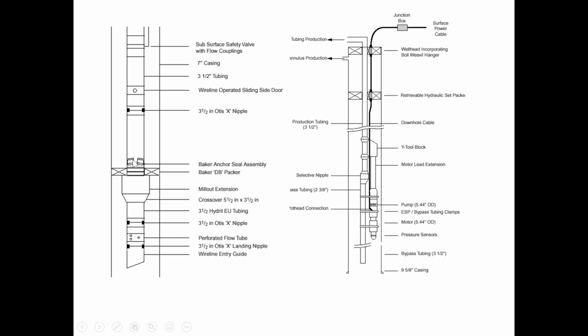And in this anchor, as I said, sometimes you just need to take the tubing out, not the packer. So we have a seal assembly, and we can pull it out from the tubing side. And then there is another location for having a plug. This is a sliding side door that creates flow between tubing and annulus.